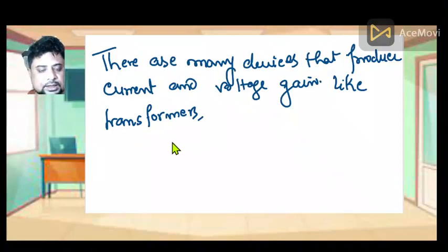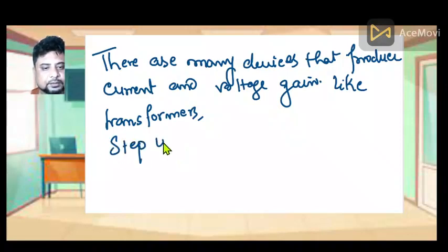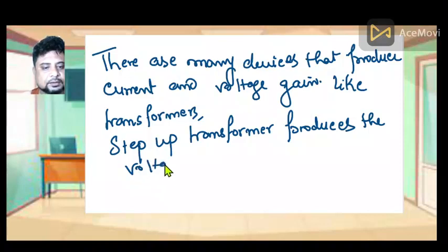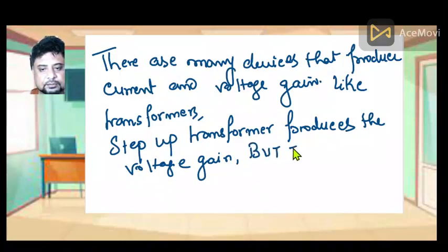A transformer also increases current or voltage. Is it an amplifier? No, it is not an amplifier. For example, a step-up transformer produces voltage gain, but it is not an amplifier.